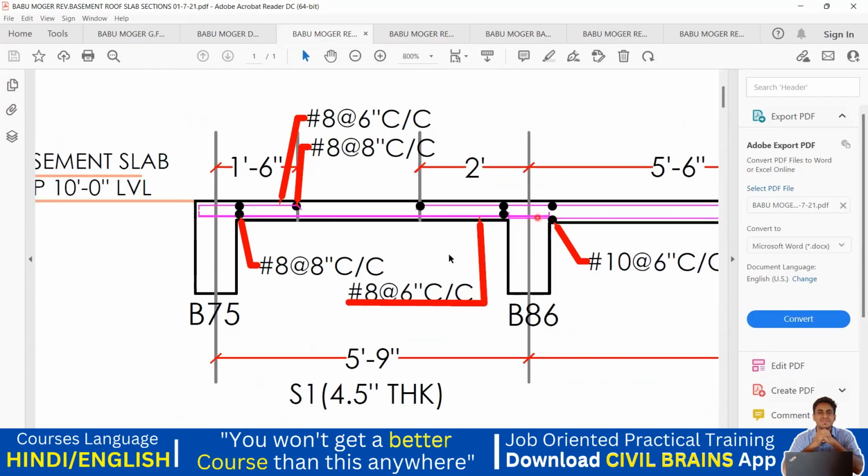Okay. So what is given here? It is mentioned in the bottom. What kind of reinforcement? You can see the marking done here. Your two markings. One, you can see that dark circle, isn't it? So that is a distribution steel. I mean, not a distribution steel, because if it is a two-way slab, both are main steel. But for our understanding, I'll use a term called distribution. But remember, if it is a two-way slab, both are main reinforcement.